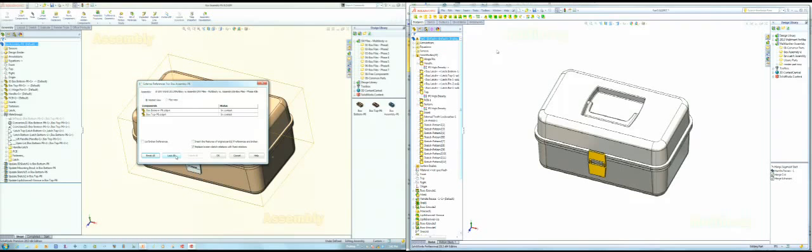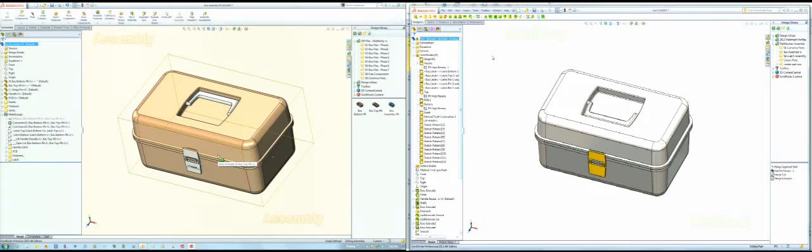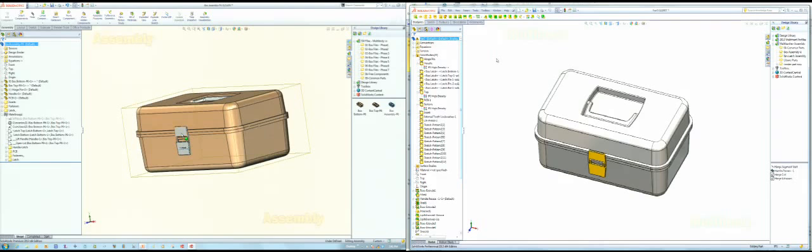And this was, I think, new in 13, where you could just do it from the top of the assembly. I hit lock them all. It's telling me they're all going to be locked. And you notice now I have the little asterisk. Okay, that's required because now when I hit rebuild, it's just not going to rebuild those dimensions. They're just frozen. Okay. So if I've done all that, then the next thing I should be able to do is create the animation. But there's one other oddity in here.